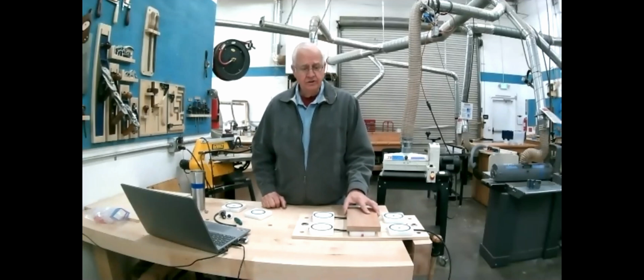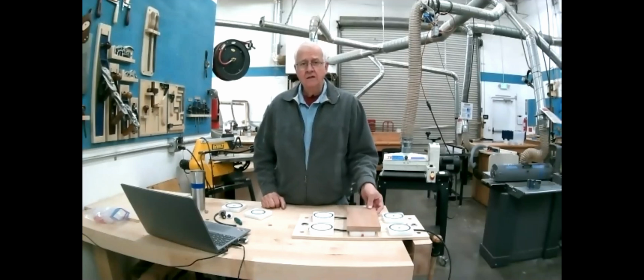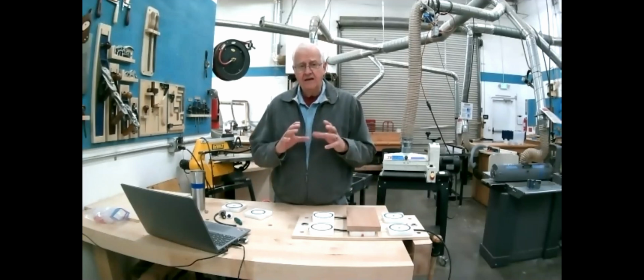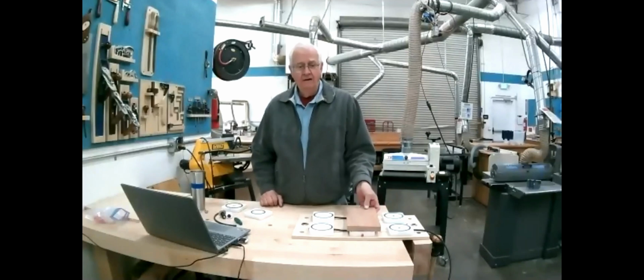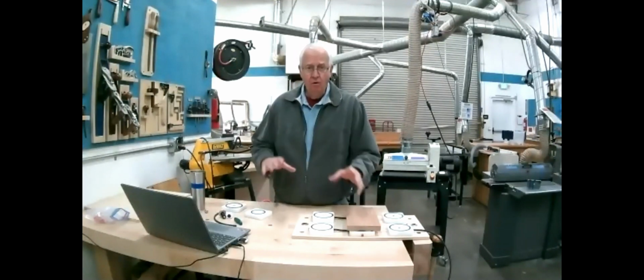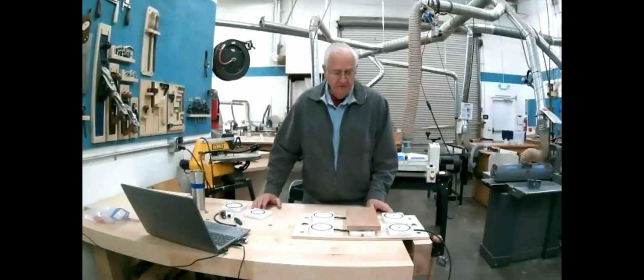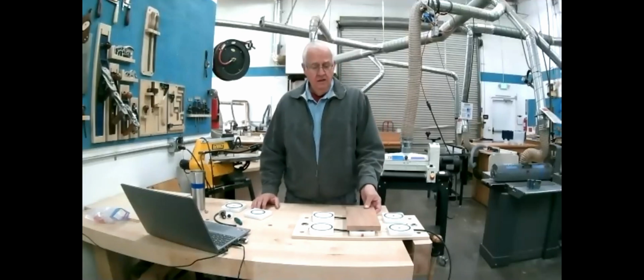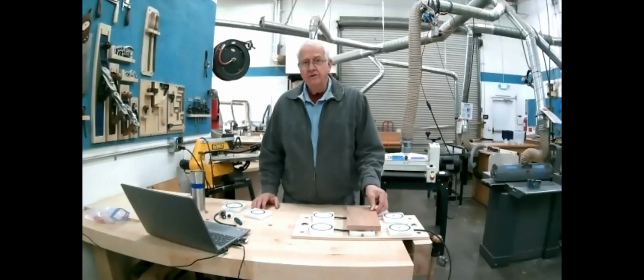And then the last area that we haven't done too much of yet, but some people do, is you can actually use vacuum chucks on lathes. I've seen that done. I'm amazed at how well it holds, but it does work. We haven't got that set up here at the shop yet, but it's something that you can do and is done quite frequently. Nice for bowls, and the turners can tell you more about that than I can. So those are the reasons you might want to use a vacuum clamp system.